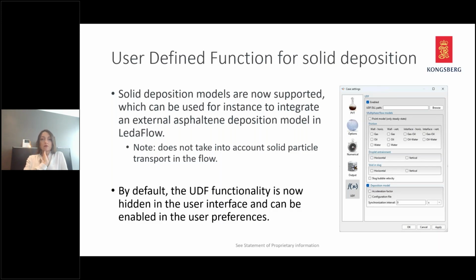Finally, regarding the model improvements, we have expanded the user-defined functionality such that LedaFlow is now supporting solid deposition models. This can be used to implement your own model for solid deposition on the pipe wall, asphaltene or wax.